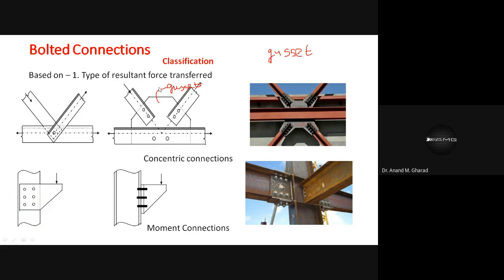Purpose of the gusset plate is to provide the complete connection of two or more members. So you can see there are three members that are getting connected at one particular joint. So it makes a joint. Okay, whenever such diagonal members are to be provided, in those cases, gusset plates are very, very useful. Got it? So over here, what do you see?